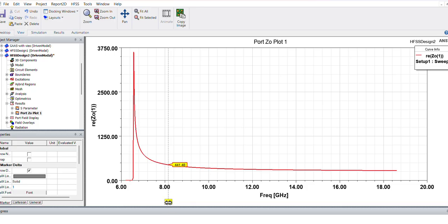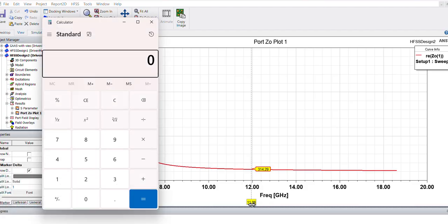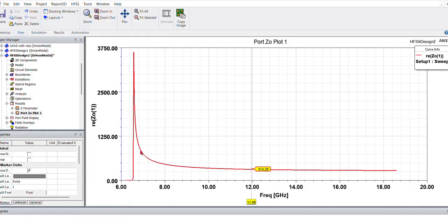But once it is at 8.2, the recommended zone, 433 ohm, to the end of this zone, 314 ohm, the ratio is much less. So that is much more useful. 433 by 315 is 1.37. Instead of earlier it was 2 times. In this zone there is a 50% reduction; in this zone only a 37% change.